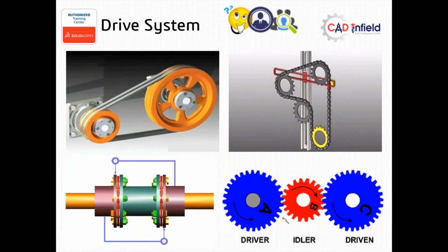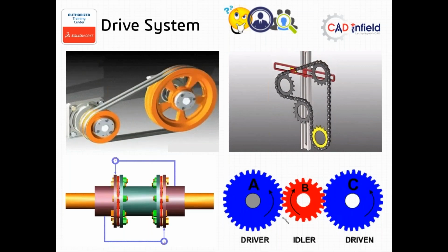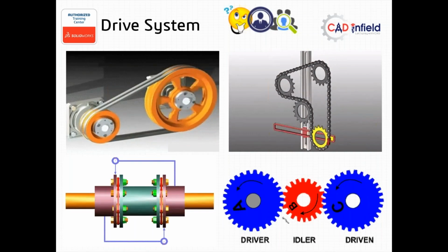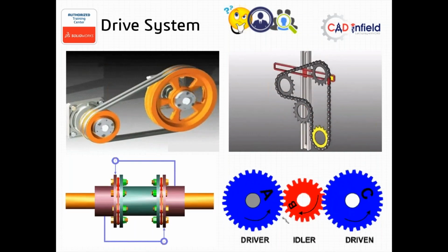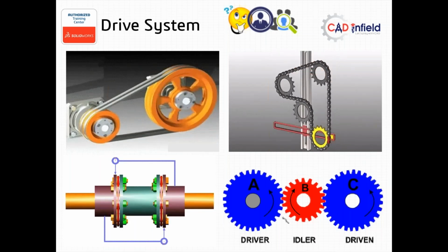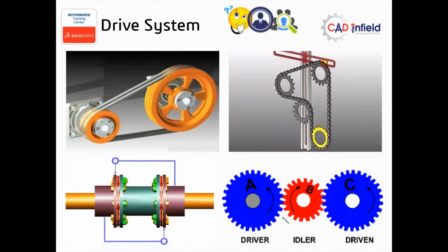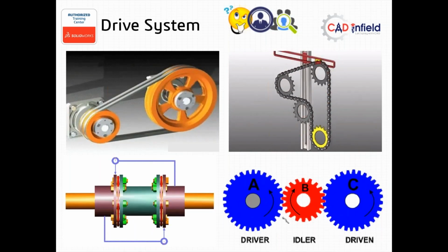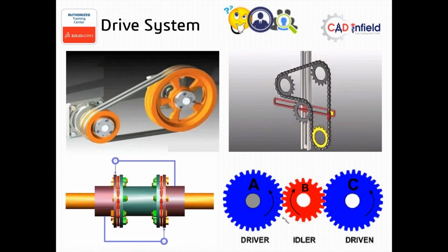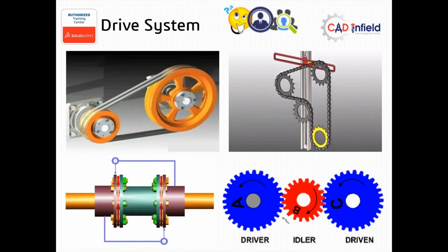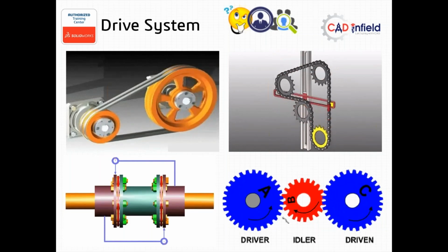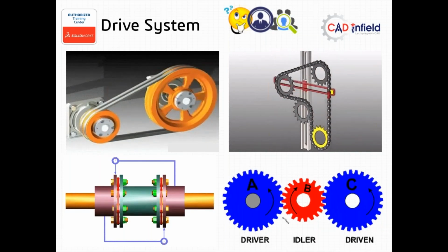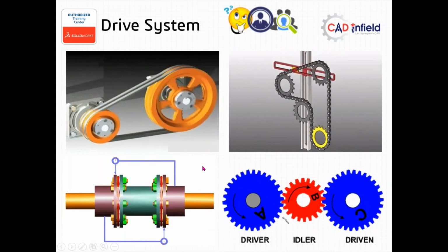Because if you have a sufficiently long distance, it is impossible to design the drive gear and driven gear, and we do not have the space accordingly. So we have to use either a belt or a chain for that drive. For example, a conveyor. We have a belt conveyor and a chain conveyor. A conveyor is long, 1 meter, 2 meter, so we can't generate a 1 meter or 2 meter gear for a successive engagement of the teeth. Understand, that is the most important. In a gear there is no medium associated with it.